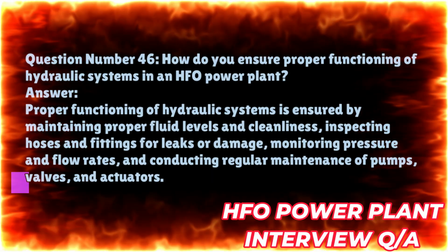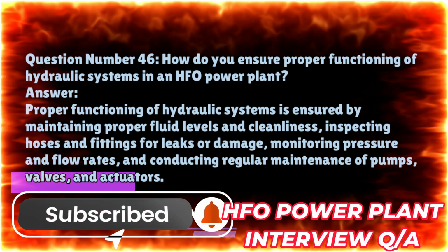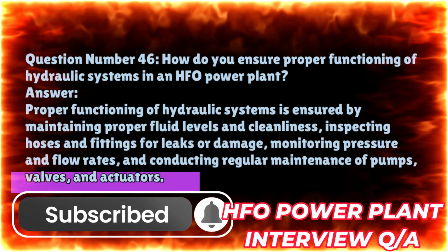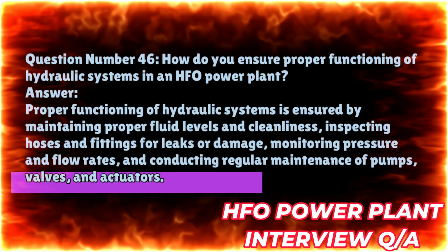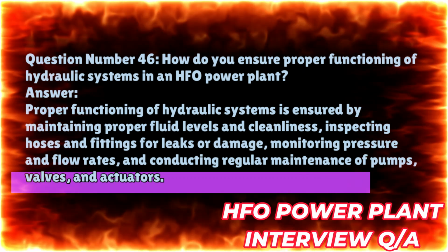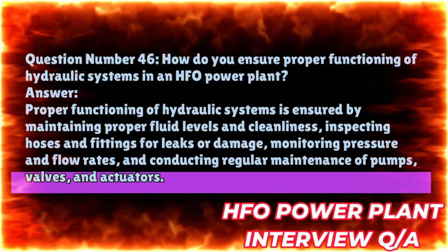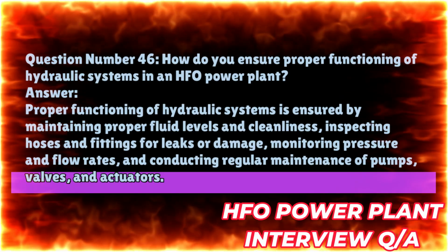Question number 46. How do you ensure proper functioning of hydraulic systems in an HFO power plant? Answer. Proper functioning of hydraulic systems is ensured by maintaining proper fluid levels and cleanliness, inspecting hoses and fittings for leaks or damage, monitoring pressure and flow rates, and conducting regular maintenance of pumps, valves, and actuators.